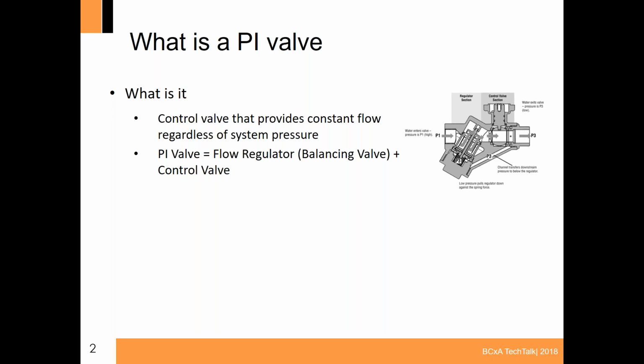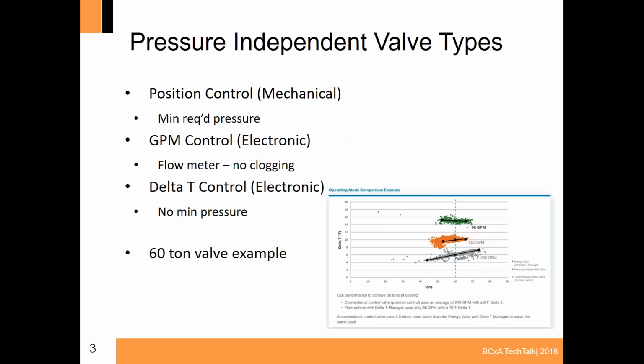So rather than the traditional model where you've got a balancing valve upstream of the control valve, and you set that balancing valve in an attempt to set a flow, and we'll talk about that, it's built in. So now we have a single device rather than a balance valve and the control valve together. And that balancing piece regulates as system pressure changes. As you know, most systems coming out today on the water side have pressure control in them rather than the old constant volume three-way valves throughout.